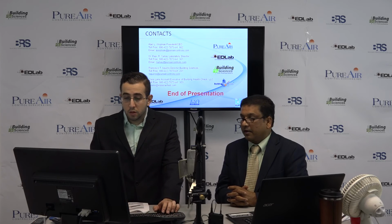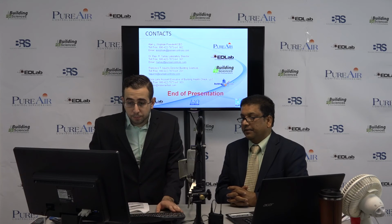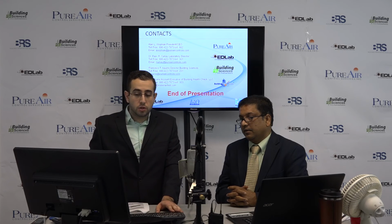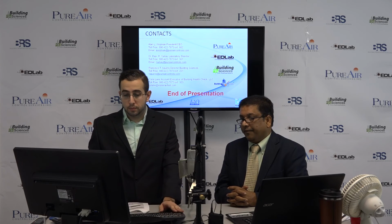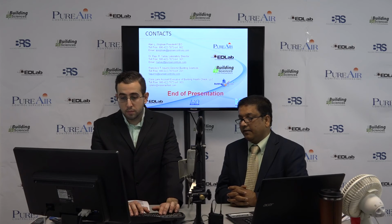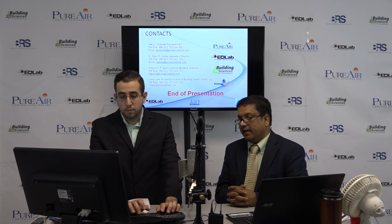Any other question you have, Ronnie? Yes. Someone is asking about how frequently sources should be sampled. As you had one slide, Ronnie, where it is recommended that you check weekly the first time, then after a 2-week interval, afterward monthly, and then obviously biannual or annual monitoring is encouraged in order to keep tabs on this bacteria and this problem.